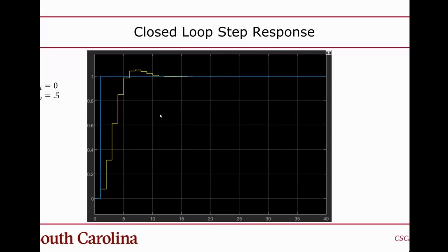But one of the things I wanted to show in here was that you could have a stable system, and if you convert it directly into discrete time and your sample rate is too long, then it could destabilize it. Obviously, I didn't show you that here, but you can imagine that if your sample time is too long, it's going to present problems, especially considering how the stability criteria for the Z domain is different from the S domain.